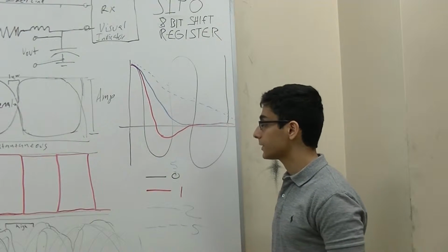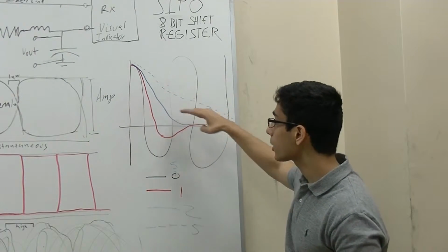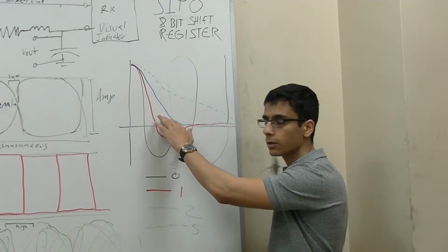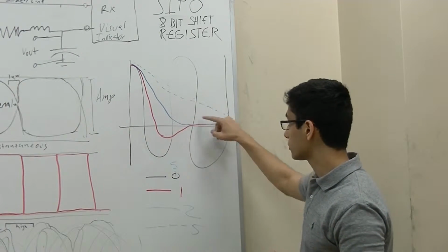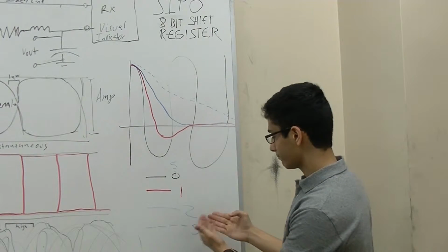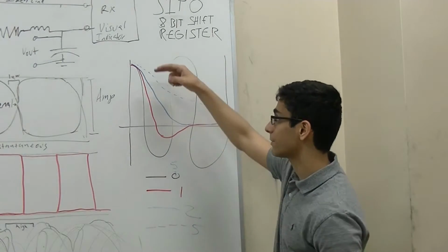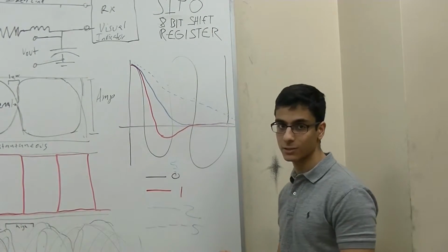If you increase the damping, the step response takes longer, but you don't see it ring anymore. So damping helps eliminate Q, but it makes the response take longer to get to 0. And again, as a comparison, if you make the damping 5, it takes even longer, but the signal is steadier.